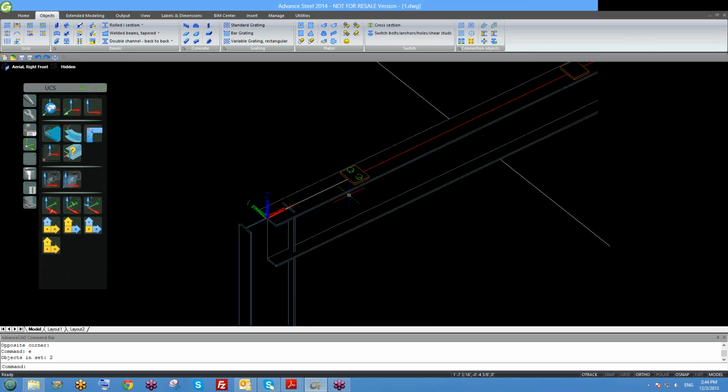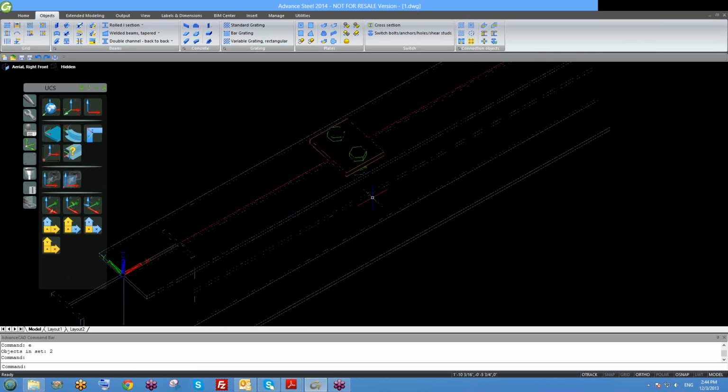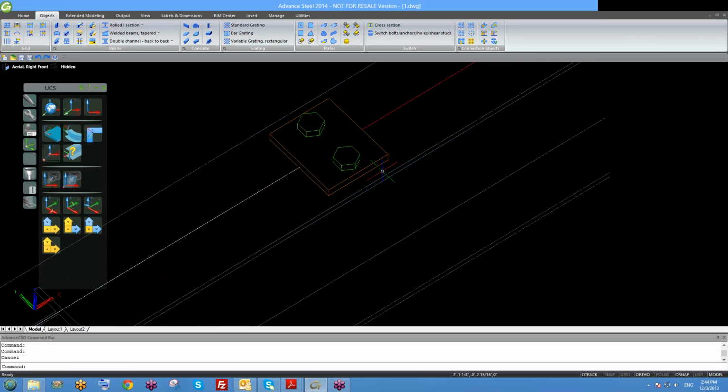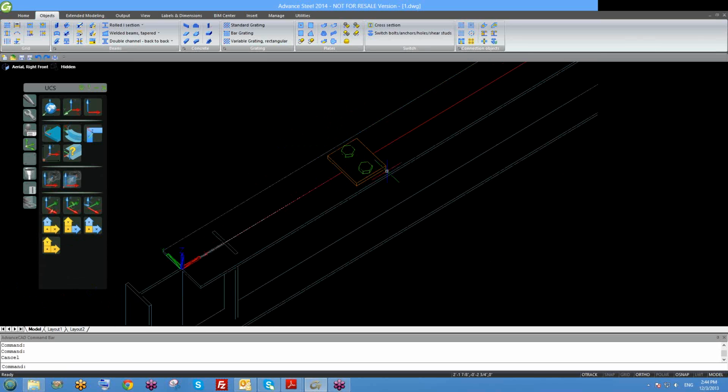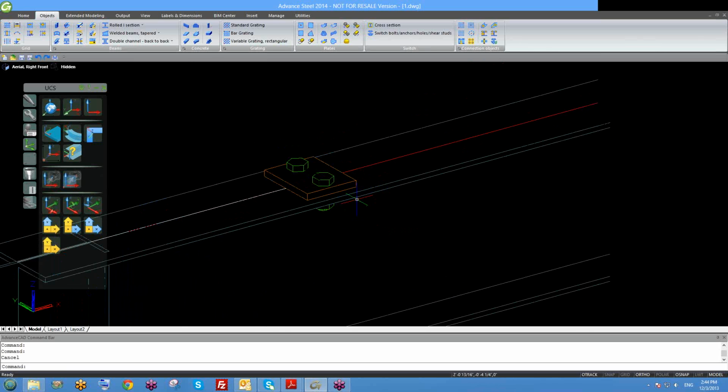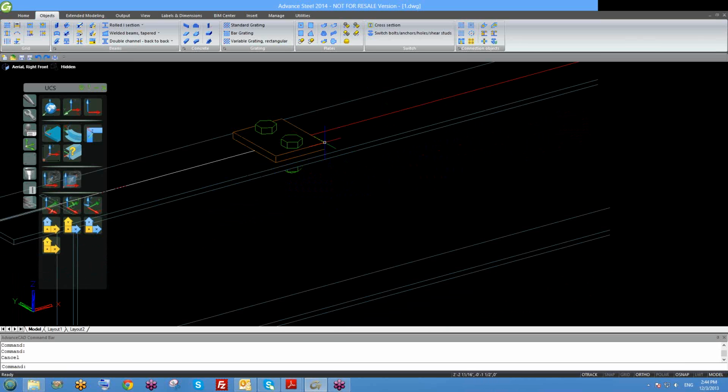I got my plate on the beam. However, when I edit that plate, I don't have the option to pick the beam. It's only picking the plate. When that window popped up, you had the plate 1/2 inch by 4. Mine was 1/2 inch by 6, but when I selected that, I didn't come up with a beam. So I'm thinking I didn't put the beam on the plate. I think because when you use the command, you didn't pick the beam along with the plate. That's why. Okay.